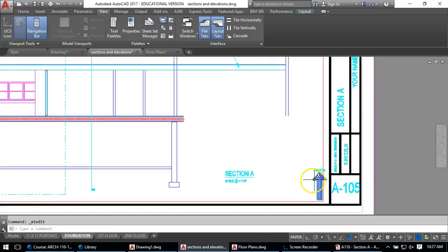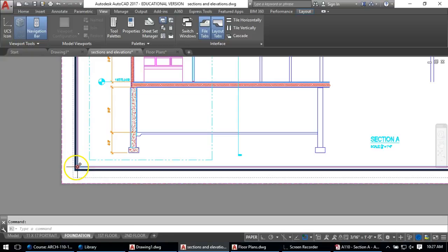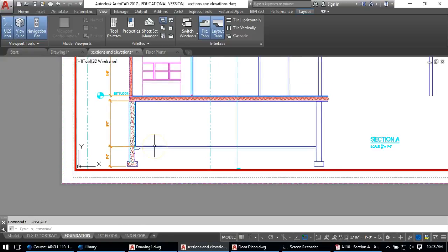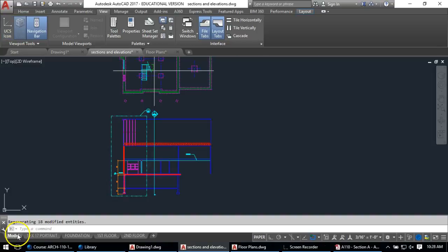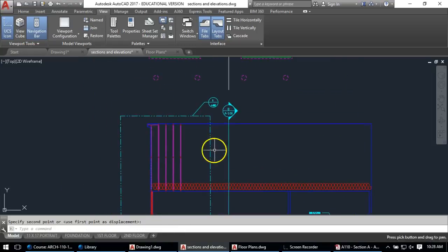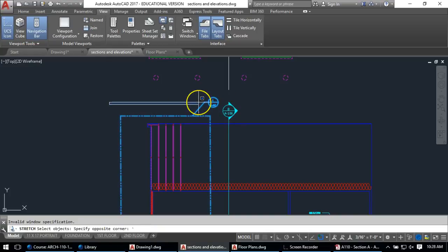No north arrow needed, so I can erase the north arrow. If I shrink this way down and pan this way as close as I can get, I can then come in the model space and make this as tight as humanly possible. I can cheat too, maybe. Do things that I wouldn't otherwise do.